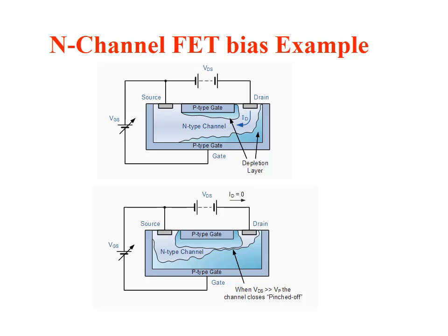So this is a side view of the transistor. These are the two P-types, you see. In here we have the drain and the source. So this blue area, from this side and from this side, is basically the depletion layer. You see, we can minimize this depletion layer by using an external source, or we can maximize it, as in the second graph. When we maximize, this depletion layer will expand from both sides, and as a result, the drain current, which we want to control, will equal 0.